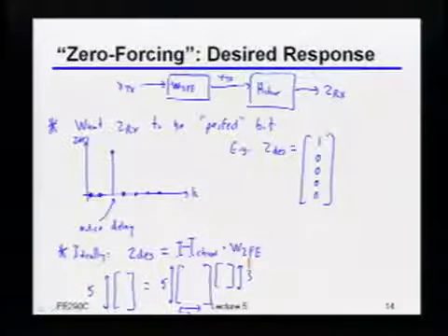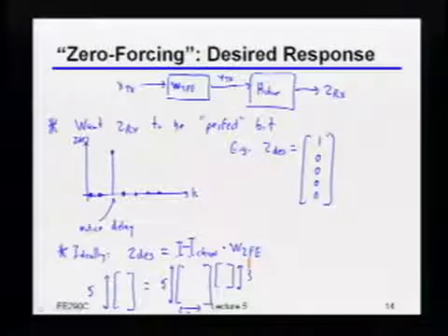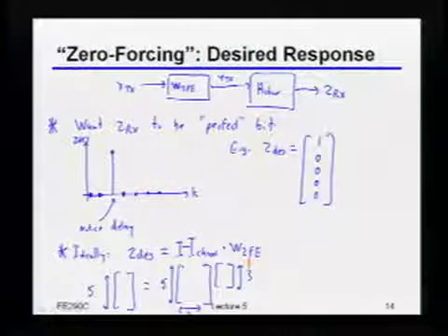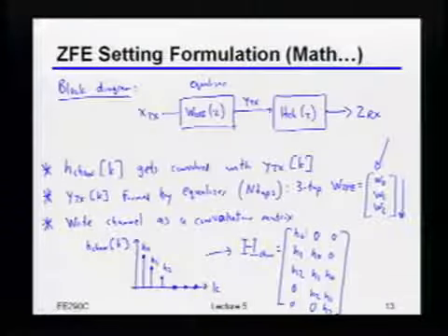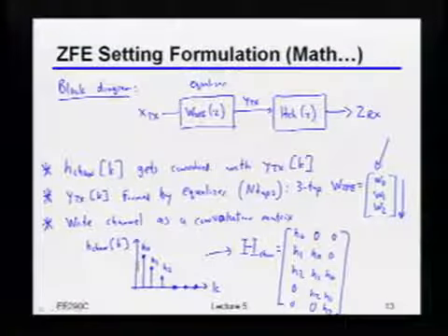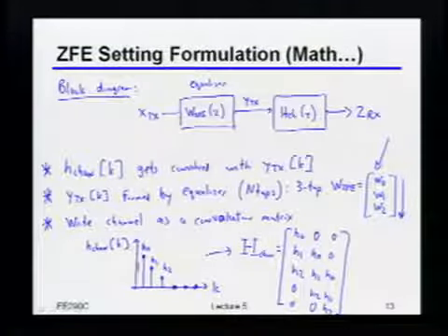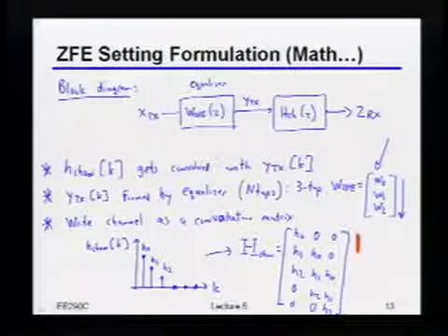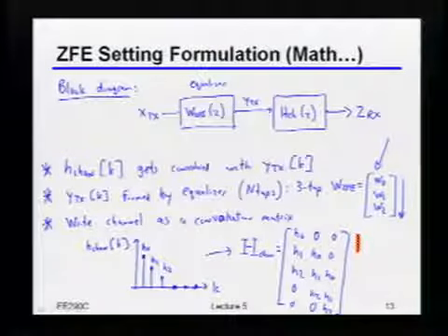Yeah, but when you're defining this H channel, you zero-pad it for the first, second, fifth, and fourth rows. But notice the first thing that's going to come out is H0, right? And if H0 is my main bit, then the channel delay is 0. So if I put a 1 right here, then the very first thing that will come out will be H0.